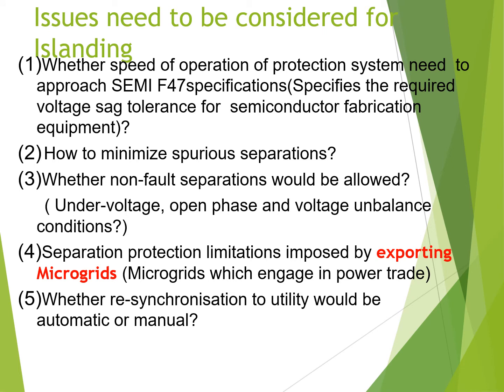The issues to be considered for islanding are, the first one, whether the speed of operation of the protection system needs to approach SEMI F47 specifications. SEMI F47 is a specification for semiconductor processing equipment voltage sag immunity. It specifies the required voltage sag tolerance for semiconductor fabrication equipment.